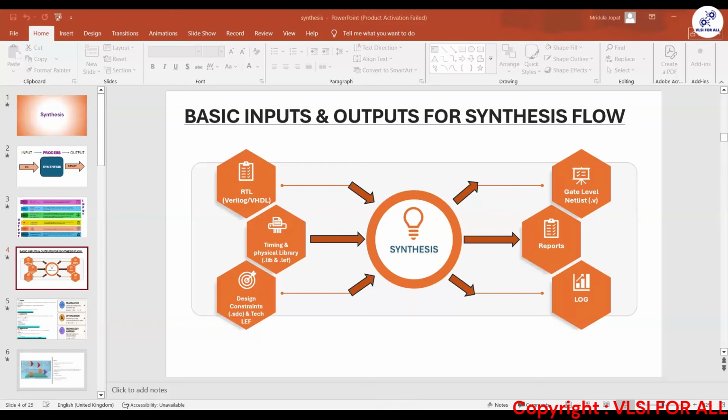If you're doing power-aware synthesis, yes, you need a UPF. If you're doing physical-aware synthesis, what does that mean? At synthesis, I am not sure what the PNR person, PNR stands for place and route, or you call it a PD engineer, will do. I'm not sure what kind of floor plan he will have, whether squarish or rectangular, or where the notch in the design will be. Earlier, they were not completely aware of what kind of floor plan was going to be used. As technology upgraded, they decided to make synthesis also physical-aware, so let's have a dummy trial with a finalized floor plan.